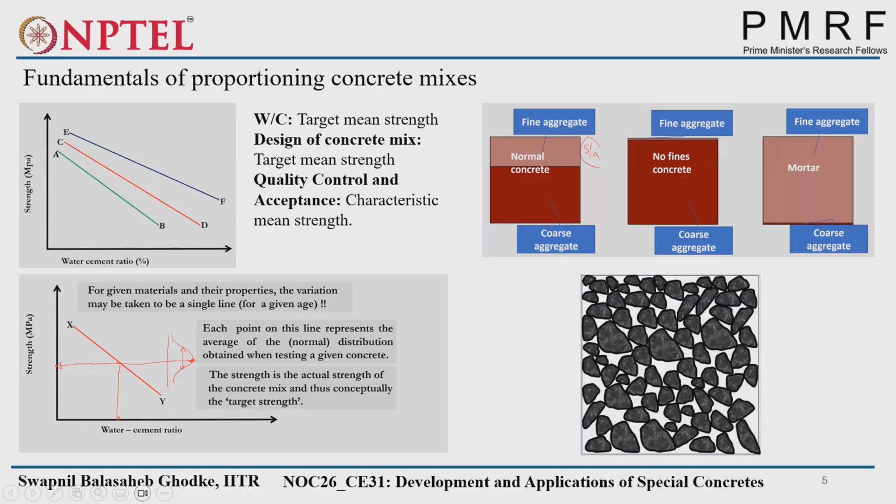So this is a block in which coarse aggregates are put in a compact position. If you see, there are some voids present between these aggregates, right? If you fill those voids with cement paste or mortar, can anyone tell me whether it will be workable if you only fill the voids? Right. So the concept is basically mortar film thickness or paste film thickness.